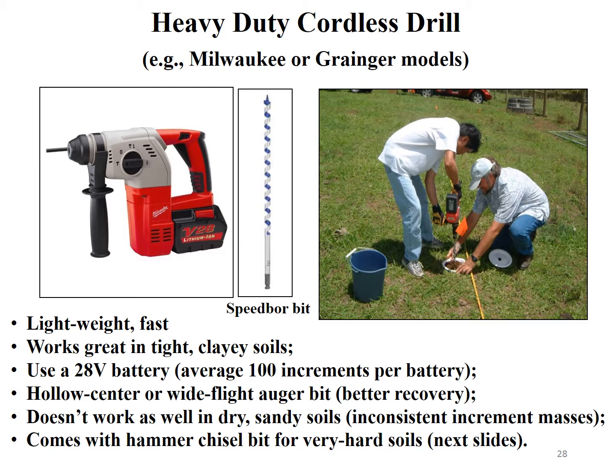So when we're wanting to use this cordless drill method, I usually also bring along a core, compare the volume or mass of soils coming out of these core using both tools to make sure that you're getting good recovery with the drill. In some soils it just doesn't work that well, and you won't get much recovery or recovery that you might expect out of a core. So you want to test that. If it works, it's a nice technique and can be fast and easy on the back.